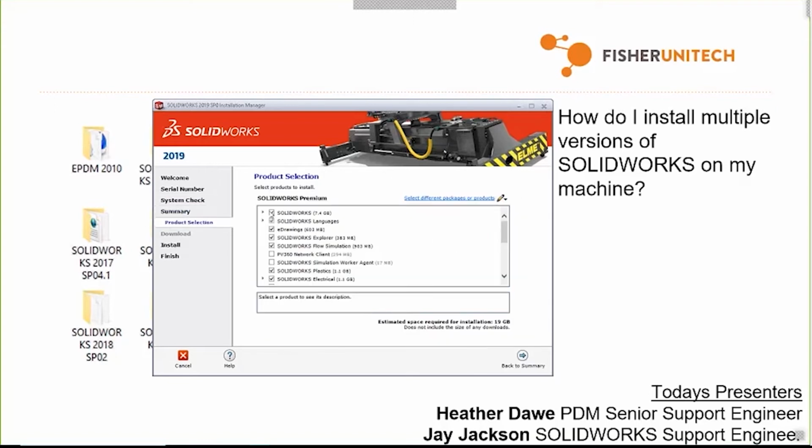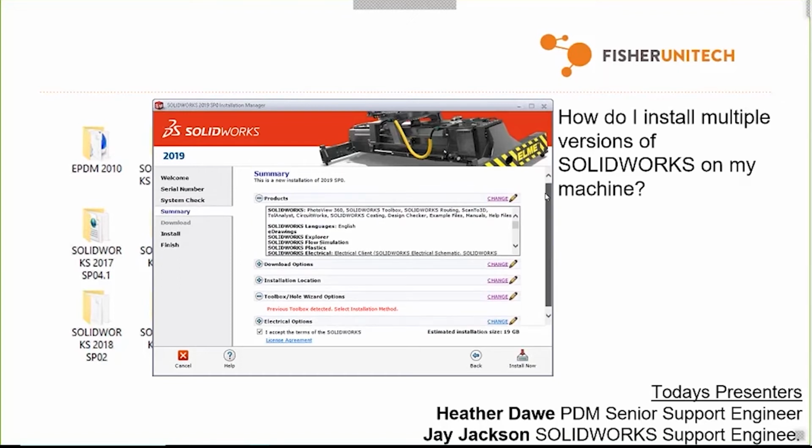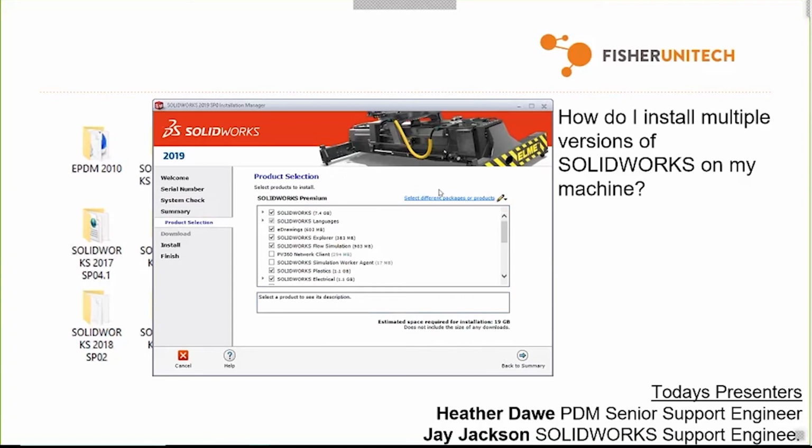All right, and so it gave me a summary of my product. So I'm going to go back to the summary just so I can look at this. I have all of these different options here on what I want to upgrade for 19, and I'm going to go through each of these. So first, I look at my product selection, and what I want to look at here is I want to make sure I have all the products that I want, but also if you guys have SolidWorks PDM and your company has not upgraded your SolidWorks PDM server yet, you're going to want to uncheck this client version.